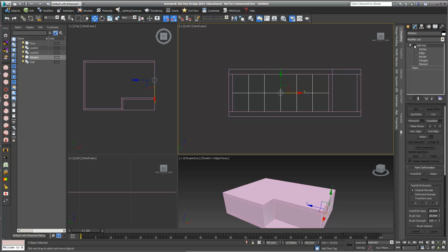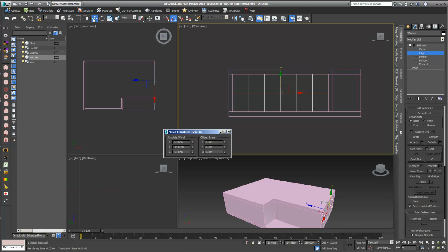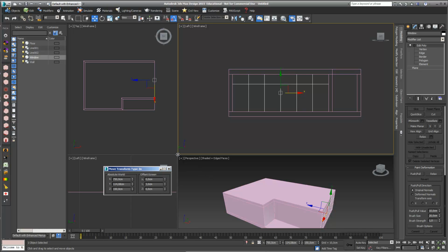then I can first move edges, for example this one, and I deselect my snap function. I move it up a little bit, so I can also enter my space. I can also move it slightly better controlled, like right mouse click, and I move it up for 70 centimeters. Sorry, of course I have to enter this in my Y direction, obviously, like this. And if I have this, nothing changed with the planes apart from that I have more segments.